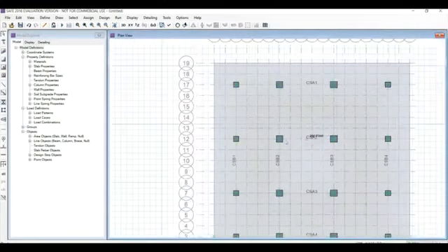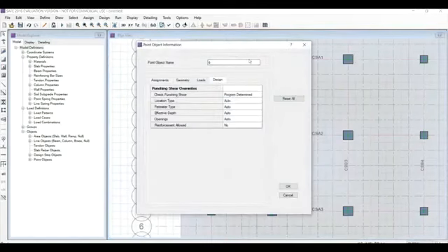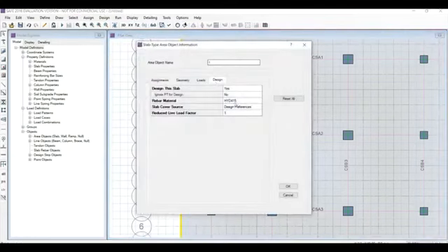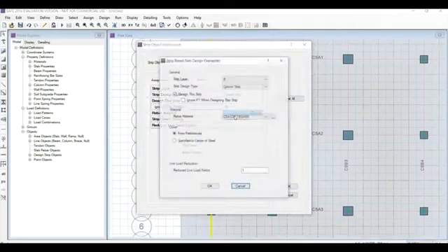And then go for the column design. Nothing is selected. One point is selected. The column rebar material is HYSD already preset. You can check every column, it will be HYSD 415. Now we need to assign for the design strip.